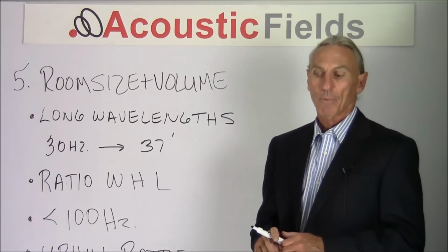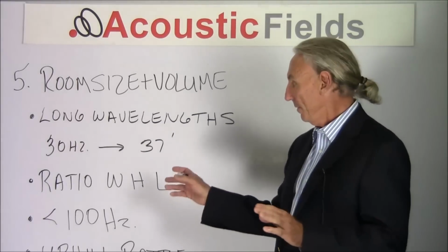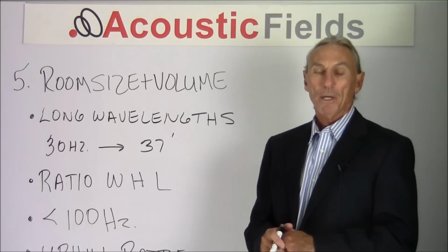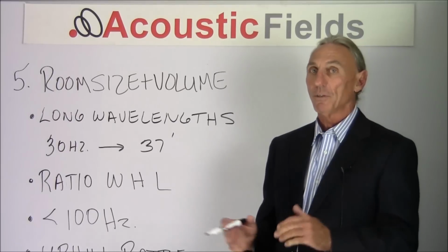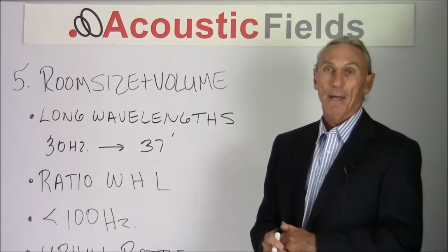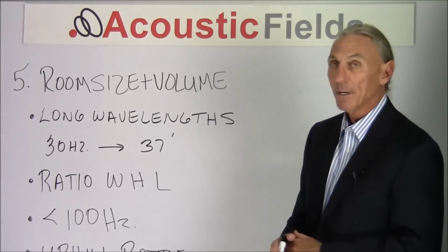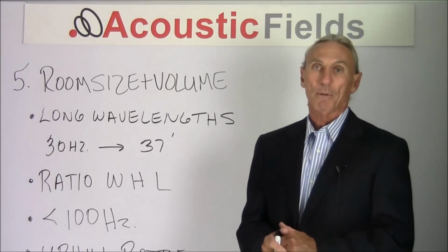So watch the ratio of width, height, and length when you choose your room, because music needs space, especially low frequency energy, and there are certain dimensions that it simply does not like. And if it's not happy, you're not happy. And you will be continually working around it, especially below 100 hertz, and it will be always an uphill battle for you.